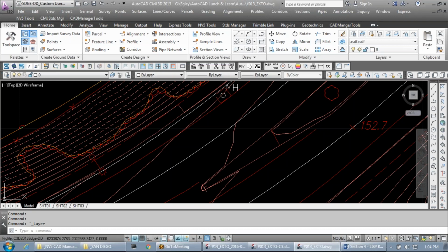Typically, I would create a layer state at major mile marks of your project, right? So when you make that first maybe progress print, I'd make a layer state so I know exactly how my layers were at that point in time. I'd make a layer state for every submittal.